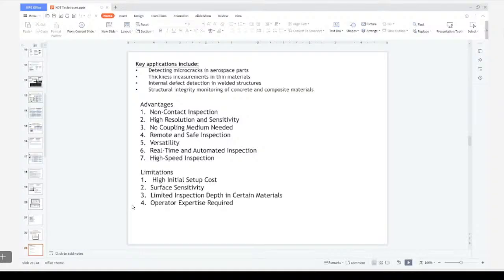I generate the resonance spectrum, and I'll compare this resonance spectrum with the standard resonance spectrum to identify whether there is any issue with respect to defects. Geometry issues also can be understood, or whether internal microstructure issues are there or not. Okay. So it's more of a comparison method. That's why it's called process compensated resonance. Resonance means you resonate the component based on its natural frequency. So that's all. This is in the conceptual stage. Here, it is again non-destructive, because I just excite. I use a sensor to capture the resonance.